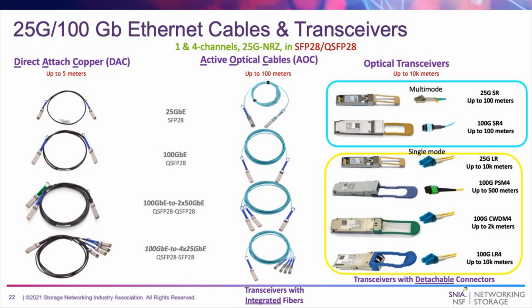And that usually is tied to multimode fiber, multimode optics, and the 850 nanometer wavelengths. And then the single mode, which is typically in the 1310 nanometer range, is denoted by yellow. And you'll see either the blue or the green on the connector. So the colors have meaning, except for the pull tabs, which is sort of a free-for-all.